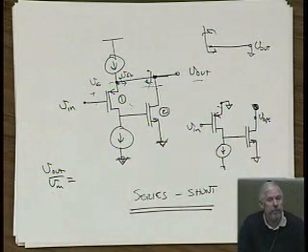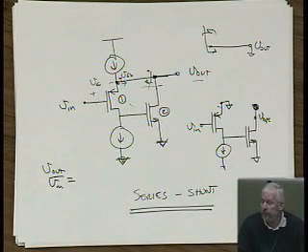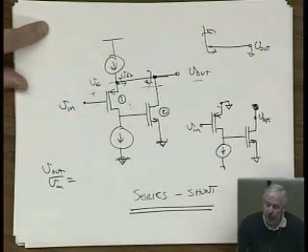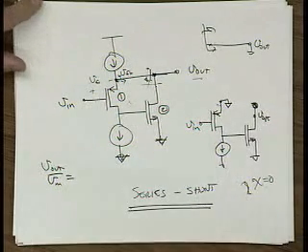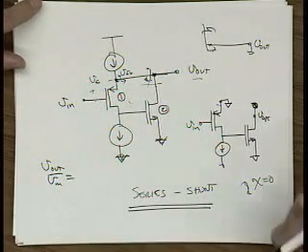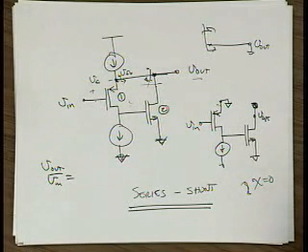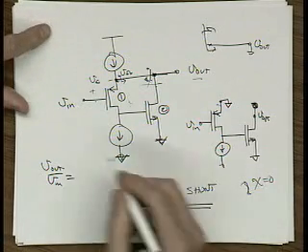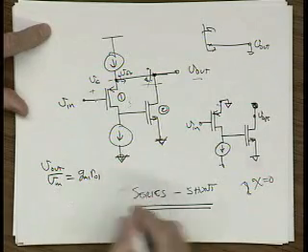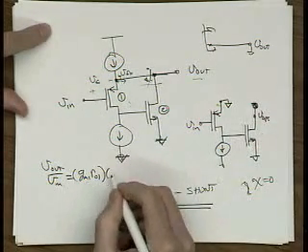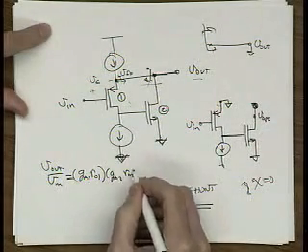Okay. Who can tell me that? Let's forget that, chi equal to 0. So what's the gain? What's the basic amplifier gain of the circuit? What is it? GM1 RO1 times GM2 RO2. Yeah, exactly right.